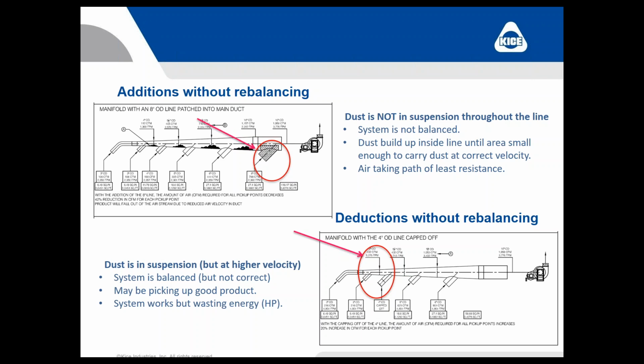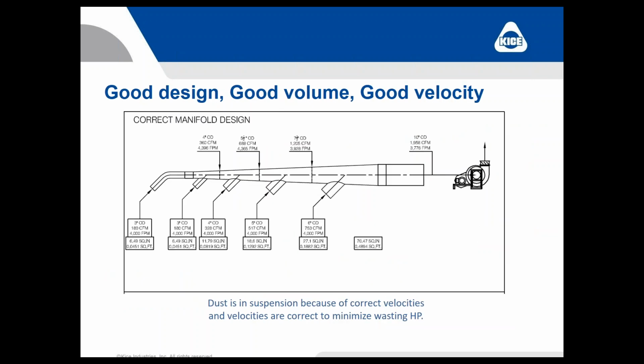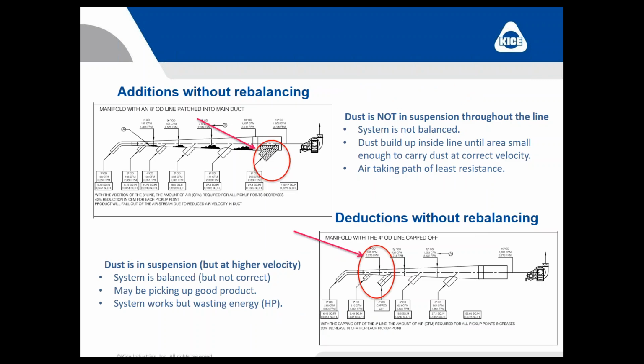You're going to hear the sound of the corn inside that line, the wheat inside that line, the plastic pellets inside that line. And then you're going to go, why do I have all this noise? Why am I losing good product? Because you're taking it to your dust control system. So backing up, there's good designs, there's bad designs, there's consequences whether you add something or you deduct something. And if you rebalance your fan after you close something off or add something, fantastic. That's the proper way to do it.